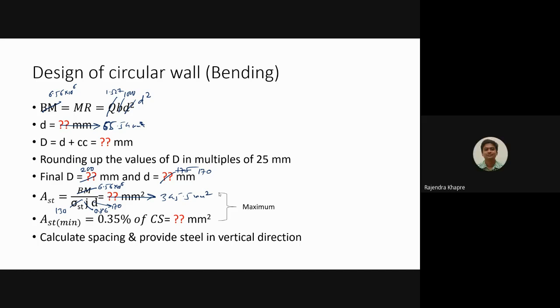Okay, that will do, it doesn't make much difference. Anyway, now as far as AST minimum is concerned, till now we are using 0.24% of the cross section area, isn't it? We have used this in GSR, in the aerator design, flash mixer design, almost everywhere we are using the AST minimum value as 0.24% of the cross section area.